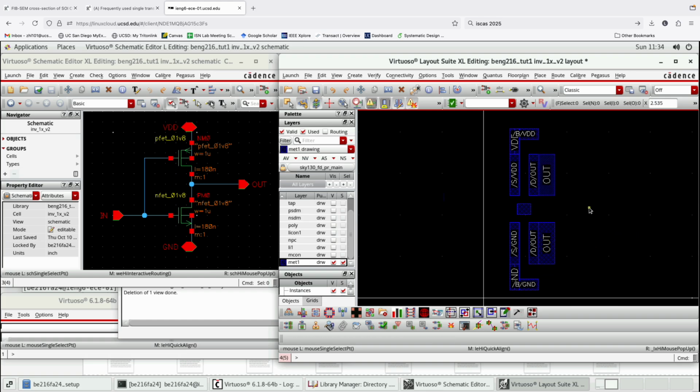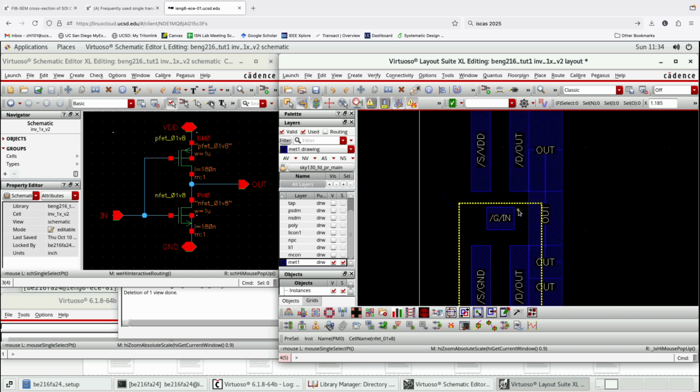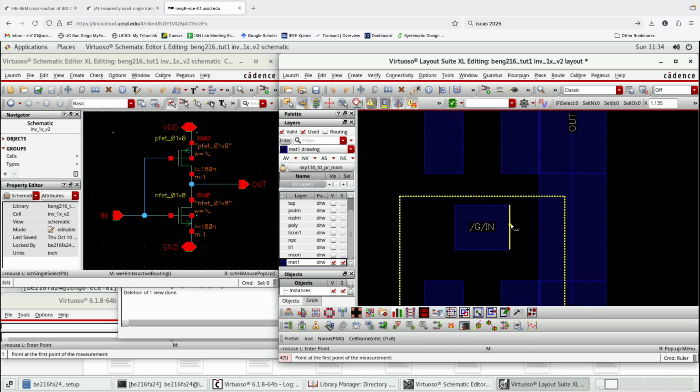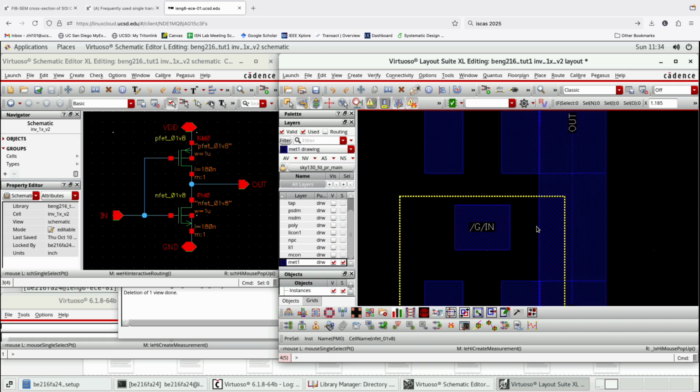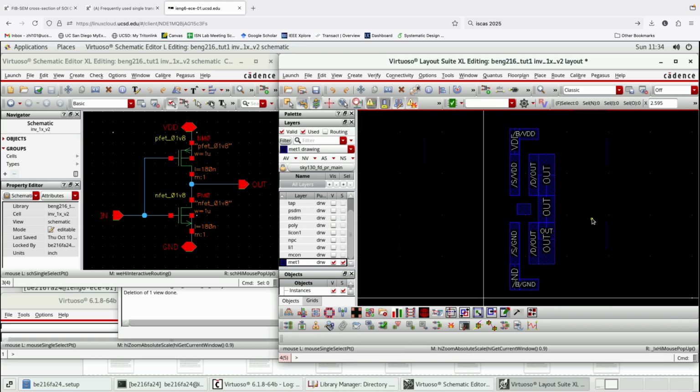And the last thing we want to do is we just need to do this connection. So here I'm using P again. And if I click on P, and I do this, bam, the connection is made. I would be a little careful anytime you try to make a connection and there's only very limited space in between. By the way, if you want to do this ruler thing, you click on K. So click K, and then you can measure anything you want. But looks like the DRC is fine with it, and then we're happy. We don't need to route it even further or anything like that.